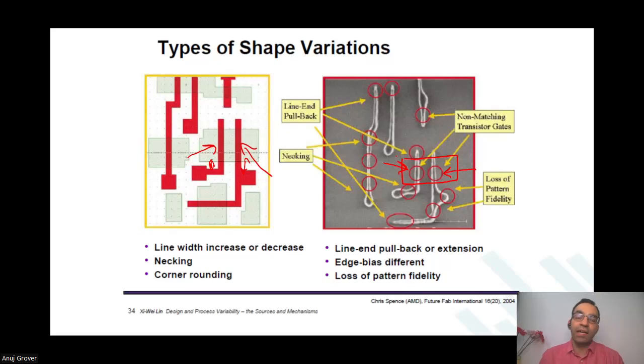The differences are evident. And to avoid these differences, you make structurally matched layouts. When you design your sense amplifiers, whichever teams work on sense amplifiers, you will be expected to do common centroid layouts with structural matching even on the metal lines, not just on devices. Such impacts, systematic variations, are completely done away with. There is no systematic offset in your sense amplifier. Even if it takes a little extra area, we will do it.